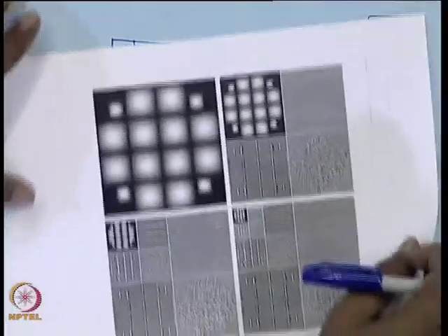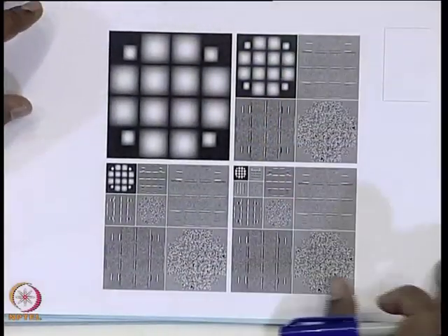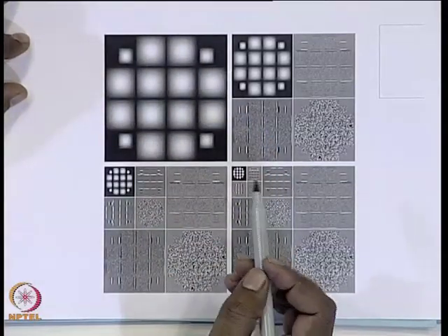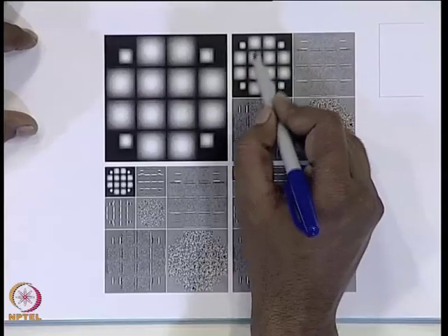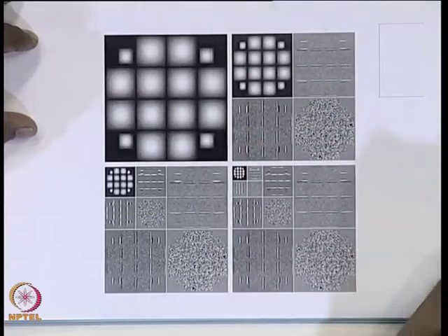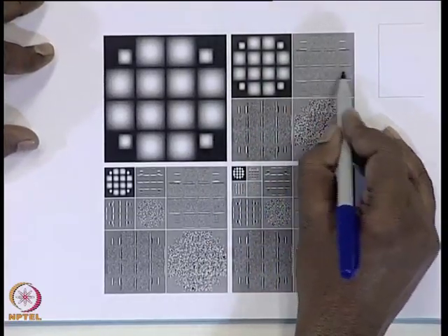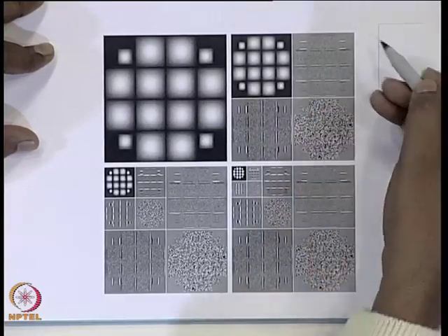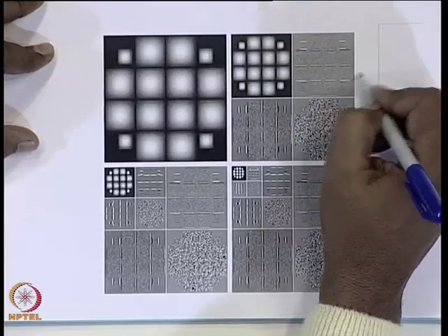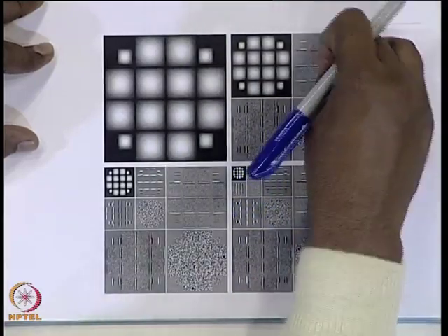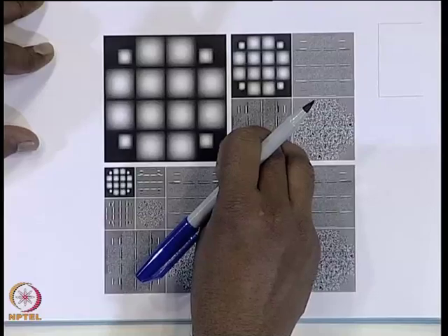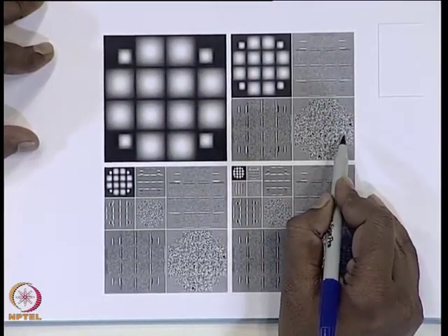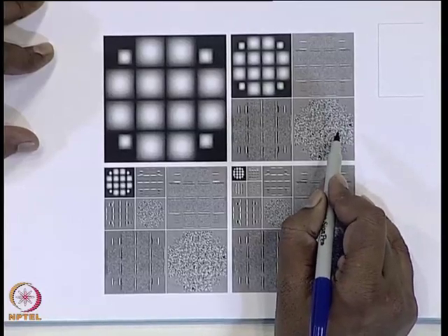So, this is an image. Suppose this is my original image. After the first level of decomposition, I get this lower resolution version of the same image. Over here, I have all the horizontal edges. Here the combination was different: high pass filtered horizontal, low pass filtered vertical. It does not matter whether I put that subband here or here, it is simply positioning. And this is the HH subband. So, this is what I have after the first level of decomposition.